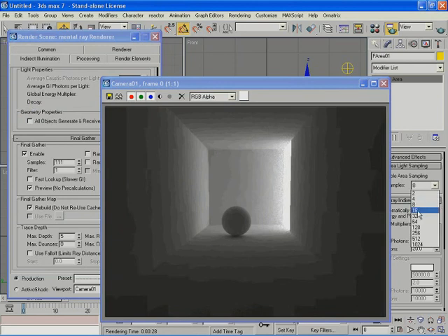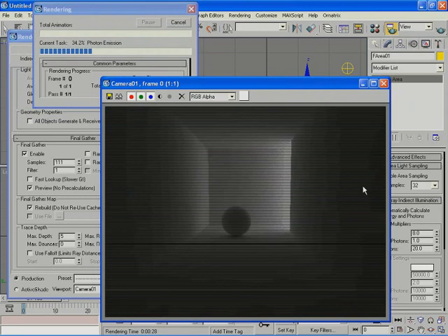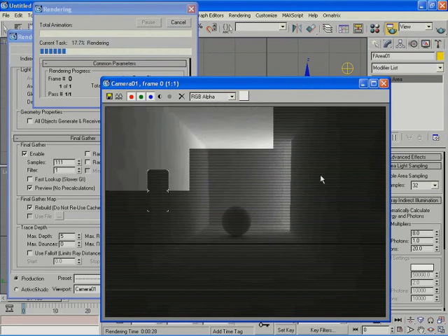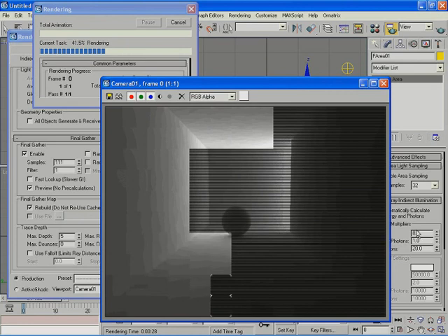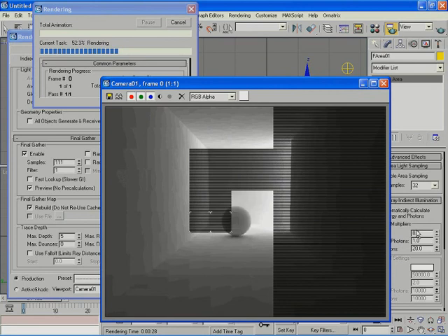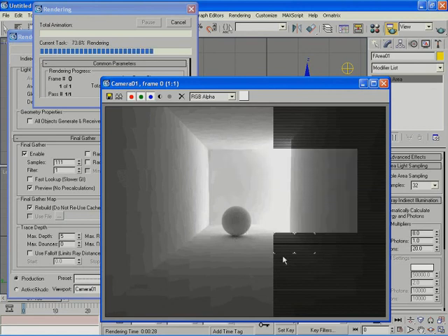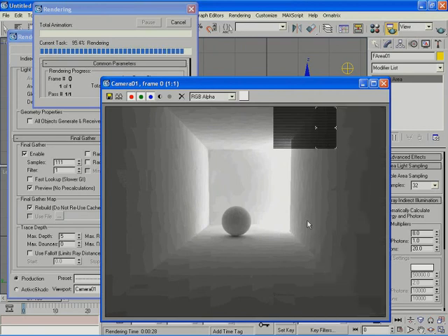Now, of course, when I increase the samples, it will take longer to render. But the shadows will be smooth. Now, 8 gave me a really bright result here, which I might leave or I might reduce. So a value of 6 would probably be a bit better. But the overall illumination is very nice because this part of the sphere is lit indirectly with the global illumination photons. So here it's a bit too bright. So let's go down to 6.5 and increase the number of photons, say to 40, and uncheck preview and check fast lookup, and that would be the final rendering for this scene.